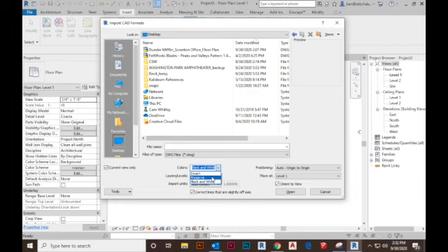In the Revit environment, that can sometimes be confusing, so I particularly like to choose black and white. I also want to insert all the layers. If you have a document from a consultant and want to pare down the multiple layers that you import, you can do this by selecting Specify. For this exercise, we're going to choose all.